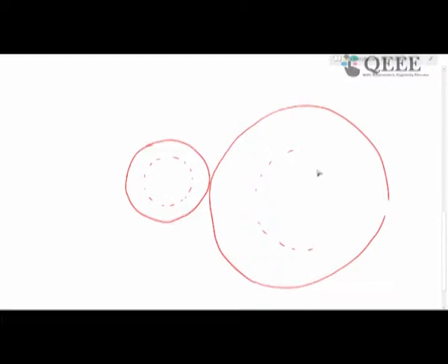It is shown in an exaggerated fashion so that the drawing is clean. This is the common tangent to the two base circles, and this is the common tangent to the two pitch circles. This is RP, the pitch circle radius, and this is RB, the base circle radius, and this is 90 degrees.